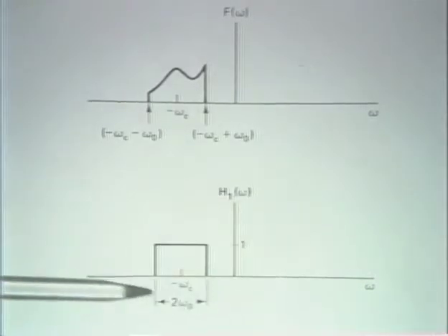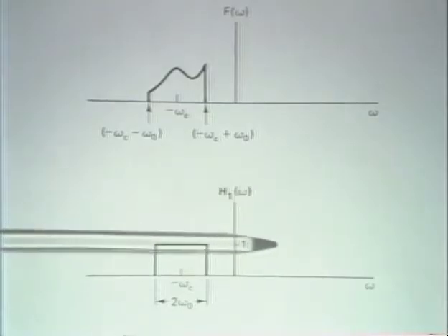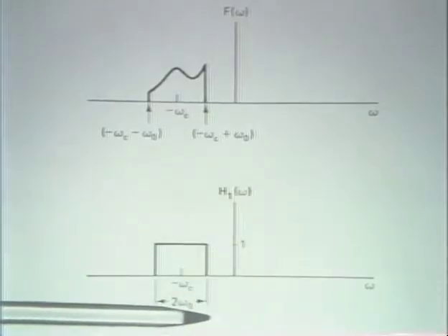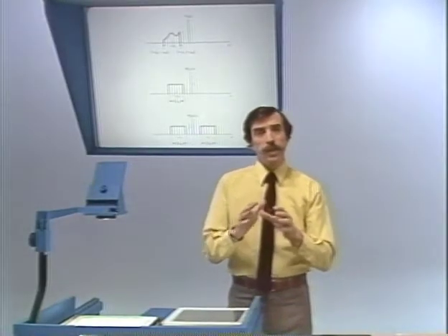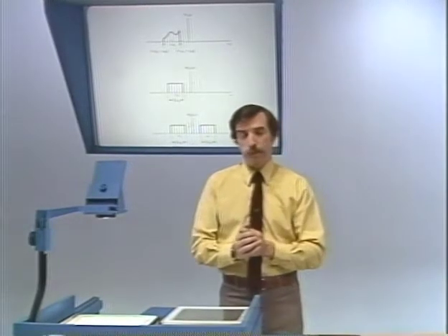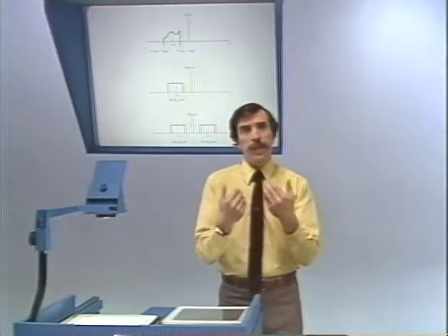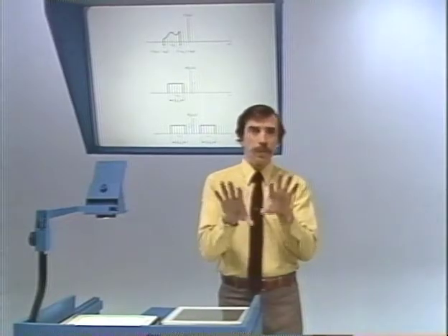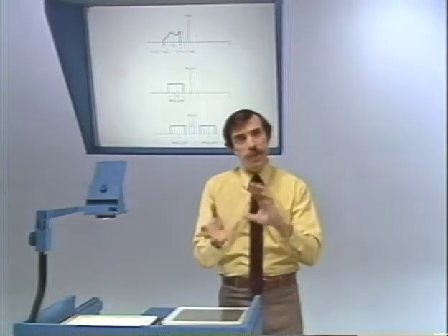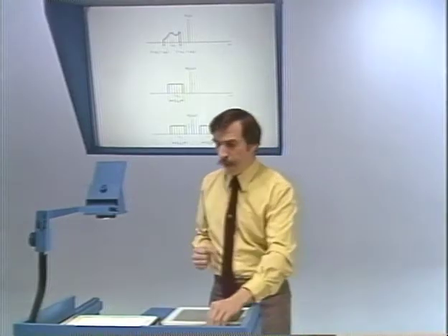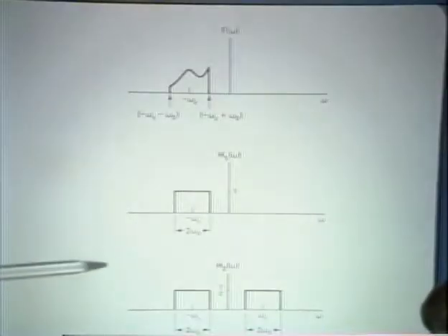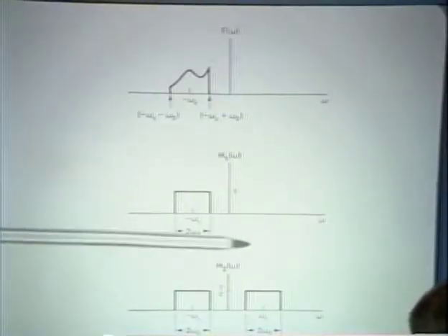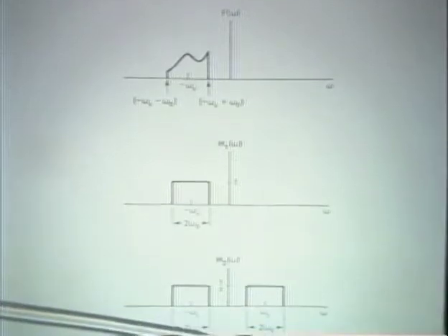Equivalently, this filter doesn't correspond to a filter whose impulse response is real. If, in fact, we add another step to this, which is to take the real part of the output, then by taking the real part of the output, we would be taking the even part of the spectrum associated with that complex signal, and the equivalent filter that we would end up with then is the filter that I indicate at the bottom, which is a bandpass filter.